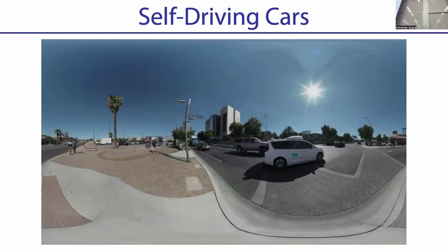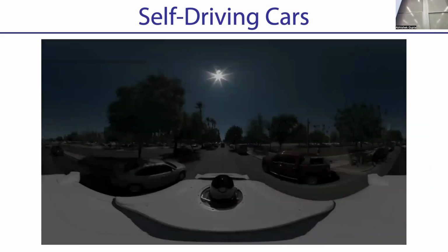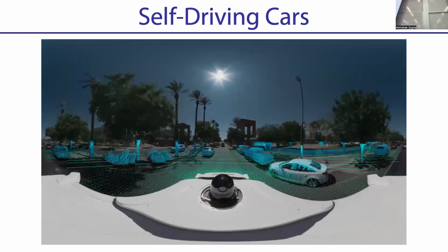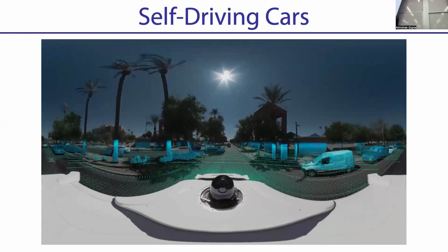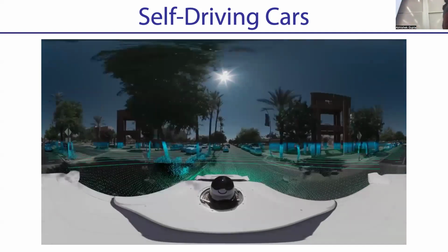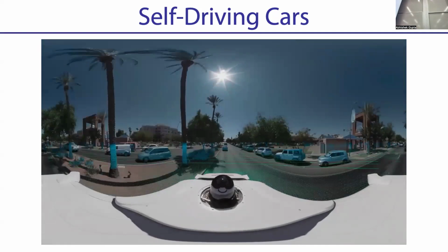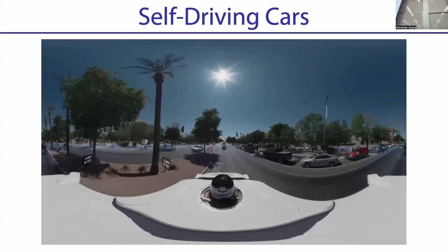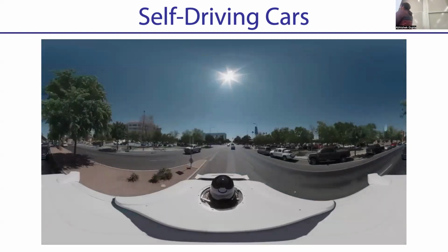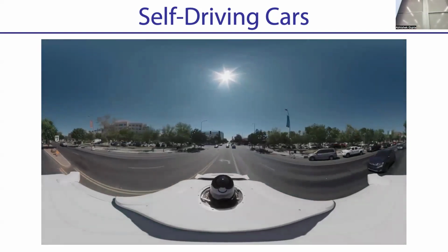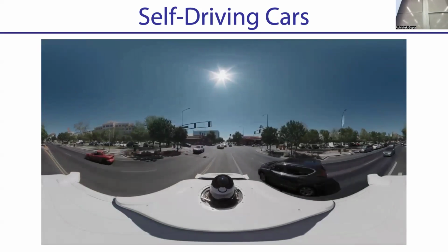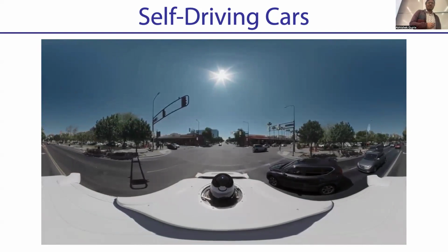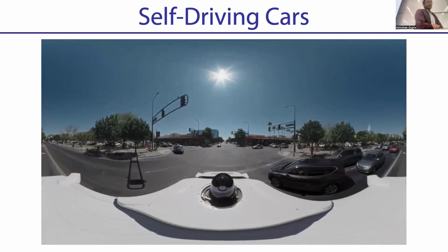Waymo, as opposed to things like Tesla, uses a lot of LiDAR. It has a lot of learning in it, but it's not a purely learning-based approach. It's learning scaffolded with other things, right? They definitely have a learning-based vision system, something that does forecasting of other cars on the road. But they also have LiDAR, which is telling you what the obstacles are. And they integrate the predictions from the learned model, grounded in the sensors that they see around them. So it's some mix of model-based and learning-based system.